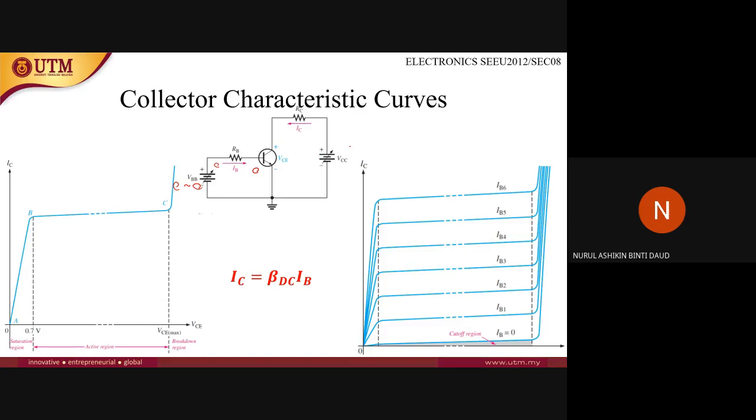And the value of VCC here is 0 volts. Assume it is 0 volts. So both the base-emitter and base-collector junctions are going to be in forward bias. Since both of them are forward biased, both are going to have a potential drop of 0.7 volts.